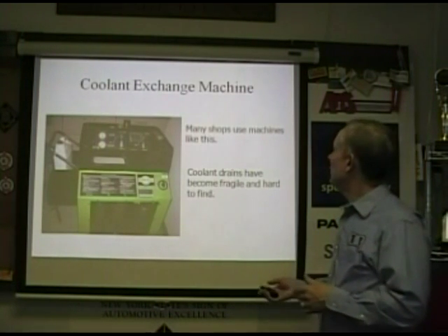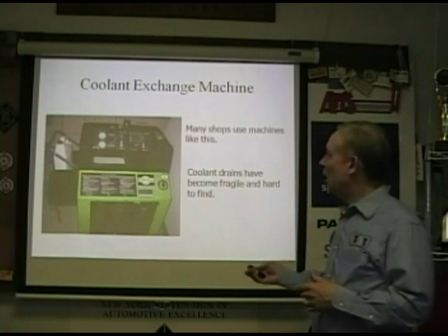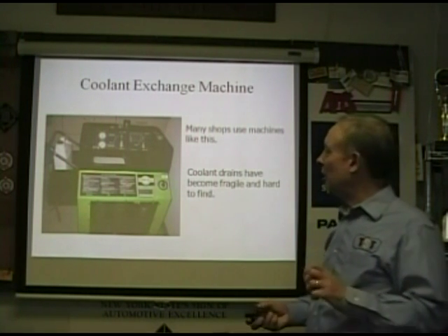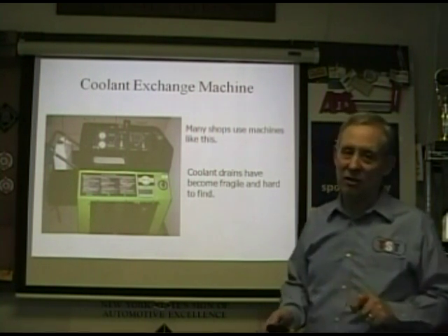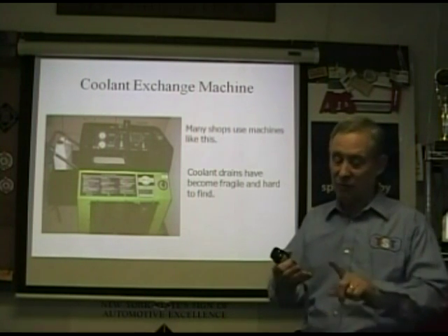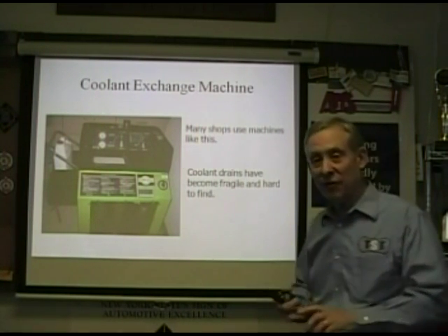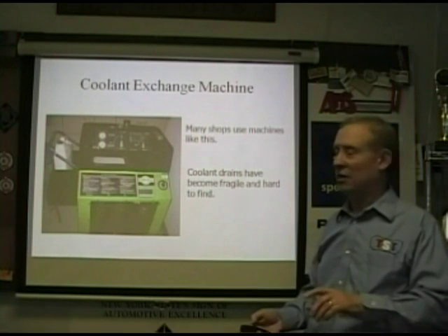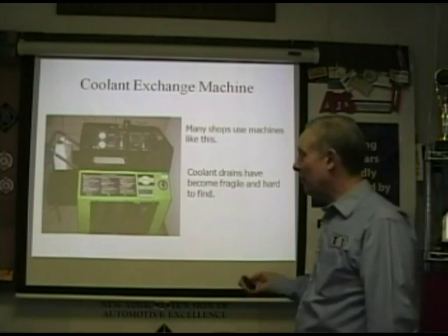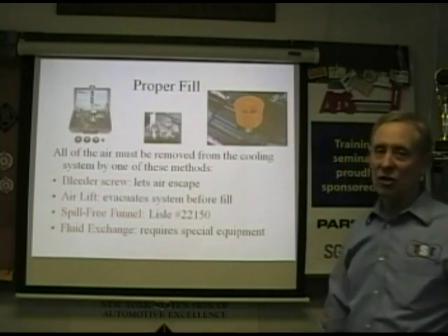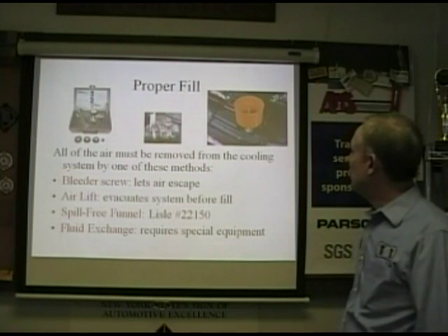All right. Many shops use machines. I'm unsure about how good this is. If you have one brand of coolant and you're very careful and you keep it clean, I suppose you can get away with it. As soon as you start mixing, all bets are off. Yeah, drain your machine out. You got to watch that stuff.